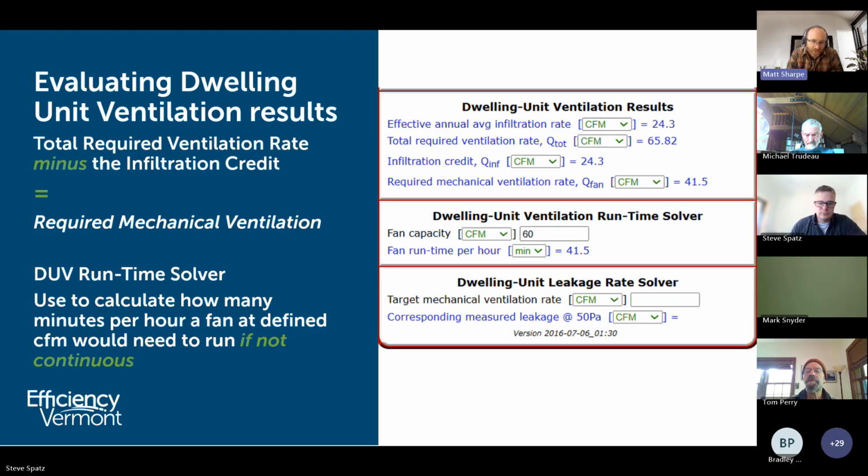It's also worth mentioning that when we're talking CFM, we're talking measured CFM, a measured result from your fan flow meter of how much CFM that fan is actually moving. The variable speed fans you have now are very good at overcoming duct pressure and can usually flow pretty similar to what they're rated at. But if you have a long, high resistive duct run, then you might get flows less than what it's rated for.